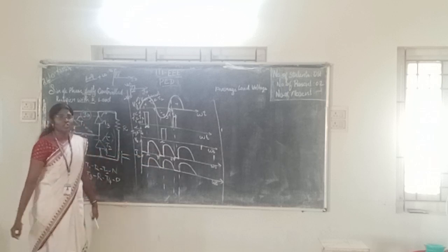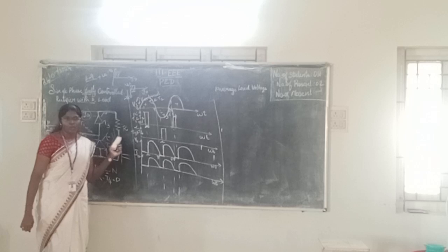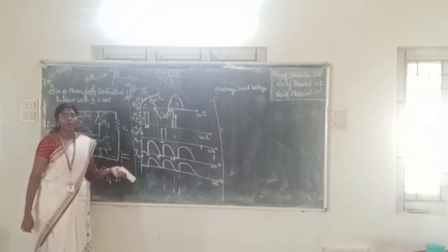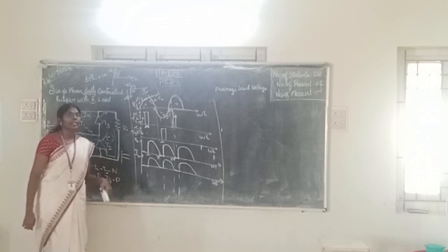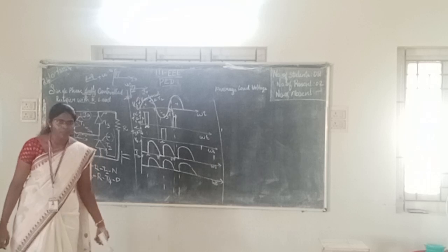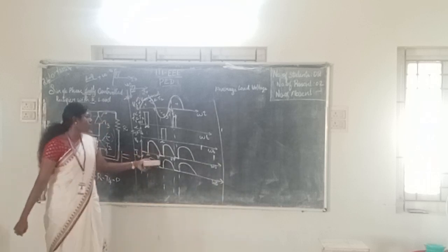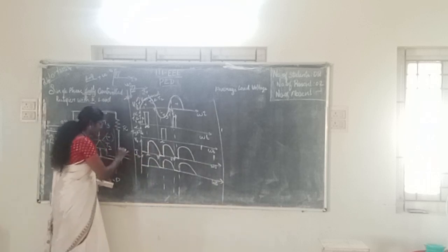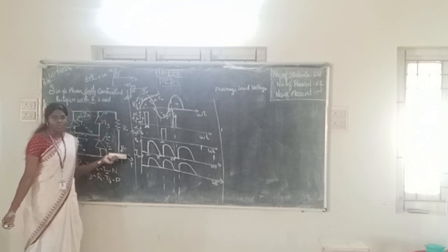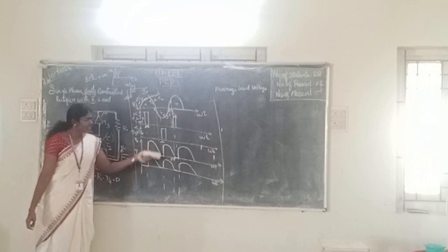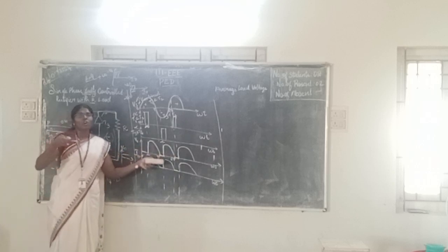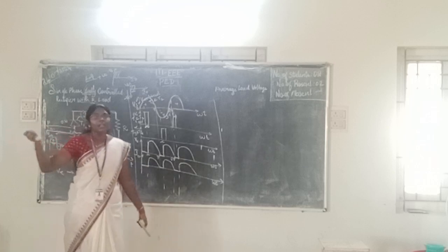So why are we changing the load? This is the R load, and next we are going for the RL load, for that purpose also. In an inductive load, due to the storage of current, the ripples can be reduced. With the resistive load, the direct current should be almost straight, but there are some ripples reaching till 0. We should not reach 0; the current flow should be direct.